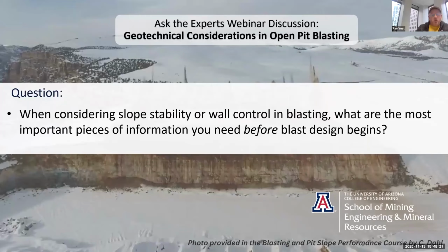And this is somewhere in between these first two pieces, this difference among different areas of the pit. You're not going to have one blast pattern for the entire pit. You're going to have areas that have different sensitivities to blasting, or different blast designs. And it's partly the geotechnical environment, but partly understanding how the rock in each of those geotechnical environments reacts to blasting.